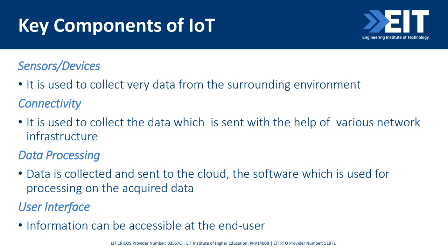Now, to build an IoT system, what do you need? You need those sensors and devices that are in the field, right? You need the perception layer. And these are the ones that will be collecting the data. Like if I'm measuring temperature, they will be collecting the temperature. I'm measuring humidity. I want to act. So this is the first thing that we need. These devices should be smart. Smart meaning they have some microprocessor in them. They can do computation, including being able to connect to a network.